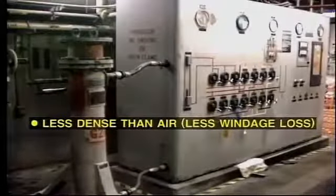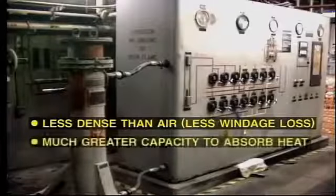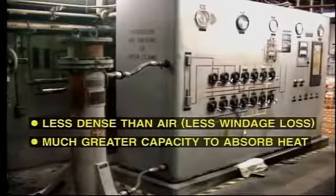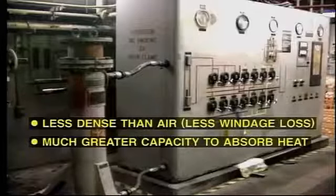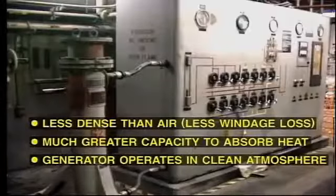Hydrogen is less dense than air, and consequently the windage loss, that is, friction loss due to rotation of the rotor, is considerably reduced. Hydrogen has a much greater capacity to absorb heat than air. Therefore, it is a better cooling medium. The generator operates in a very clean atmosphere.